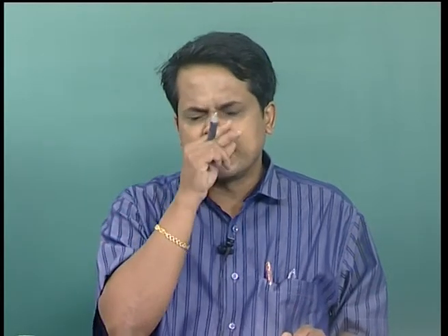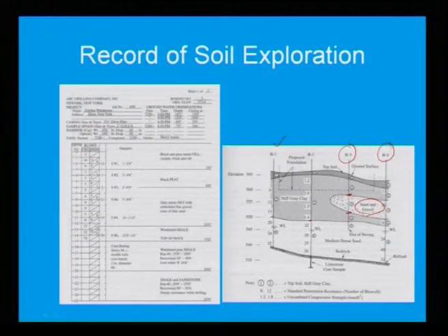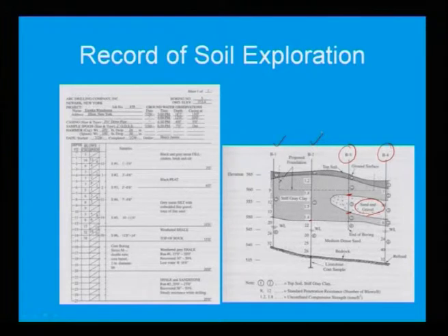You cannot say that with a single borehole or maybe 2 boreholes the soils will be the same. Look at these 4 boreholes, borehole 1 and borehole 2 are completely identical soil profile. The moment you go to borehole 3 and borehole 4, the sand patches, sand gravel is very less in borehole 3 and in borehole 4 it is more wider. This is the basic difference as far as the design is concerned, because why I am discussing these things again and again,